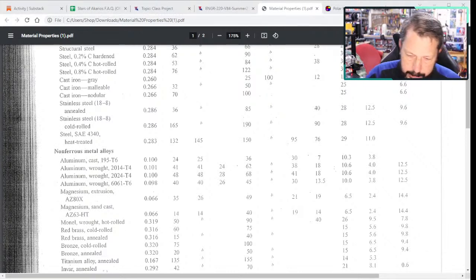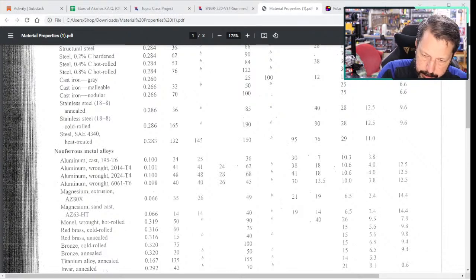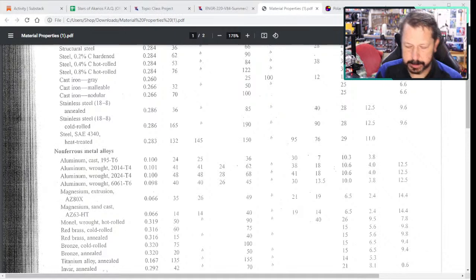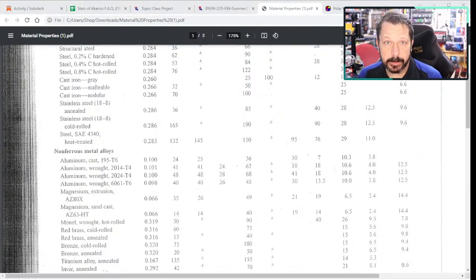We have 30 foot-pounds here, and we have the opposing direction, 50 foot-pounds here. So for this to be in equilibrium, if I cut this section up and look at the equilibrium, I need another 20 going in this direction. So this larger cyan section actually has a smaller internal torque.